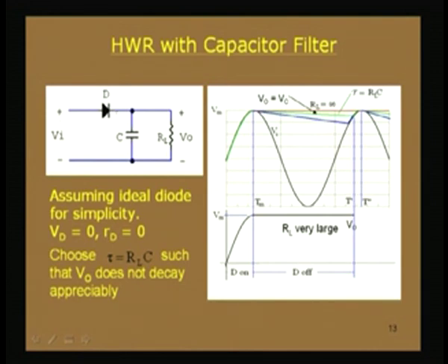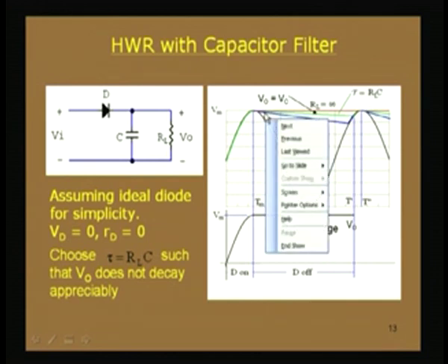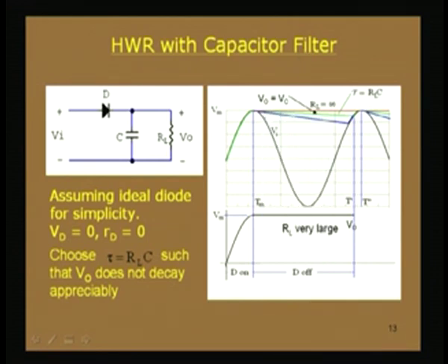Now, the capacitor voltage is Vm, the peak value, but the P side anode is having Vi, which is less than the capacitor voltage after this peak point. If we consider this point, for example, here the capacitor voltage is V naught, which is equal to Vm, but at this point the input voltage is falling down. So, this diode will be reverse biased and it will not be conducting. So, this circuit is off.